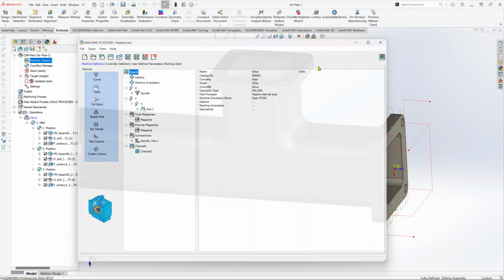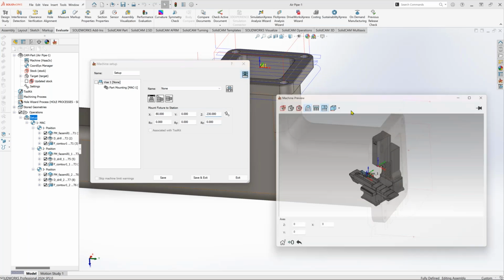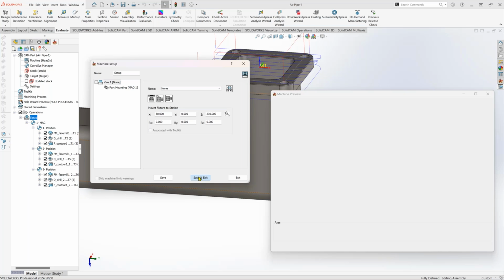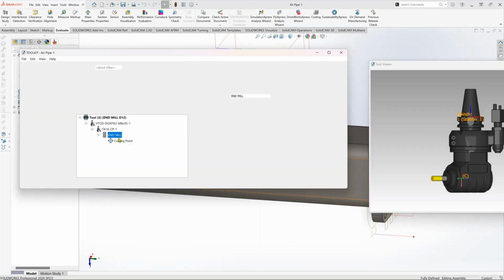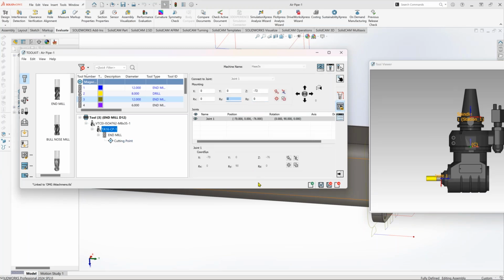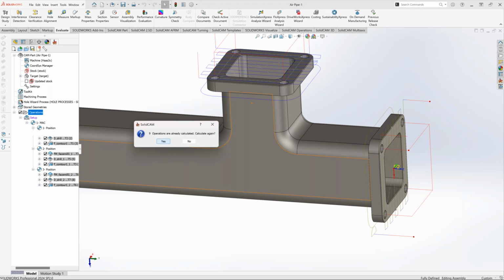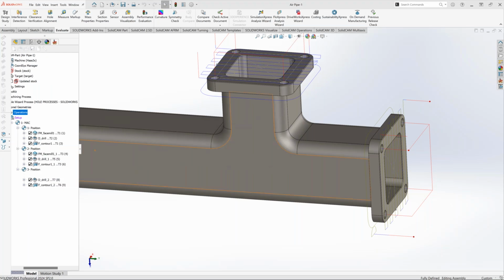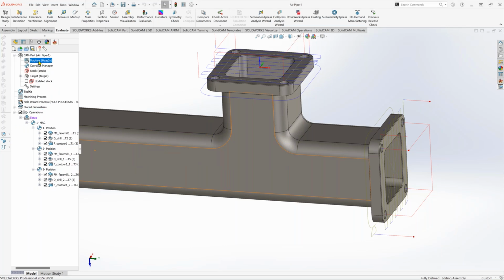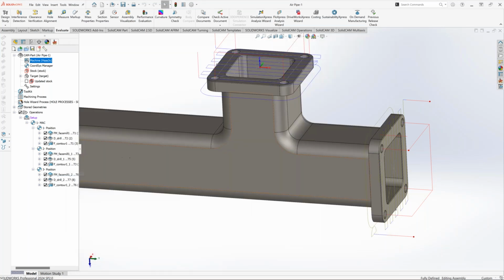I will set it back to the initial value. So I will put it to 0 degrees. Okay, I hope it will be saved. Save it. I will exit. I also return the tool to the initial position. I don't want to keep it like this. So let's put it on 0, save it, and recalculate everything. And I will cancel the plane tilting, because my machine cannot tilt the plane. So I just put a null here, nothing can be tilted. And now I have an initial state.